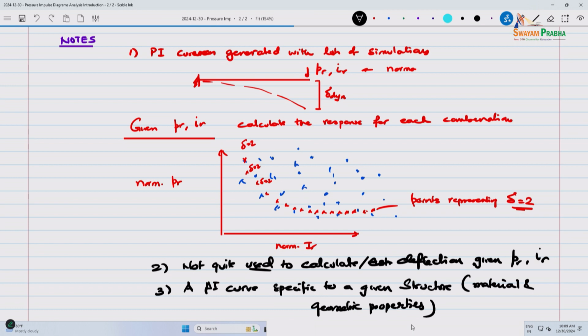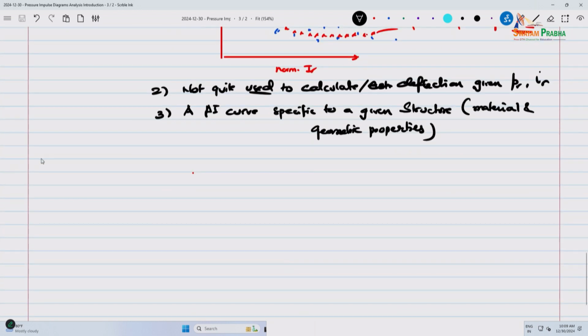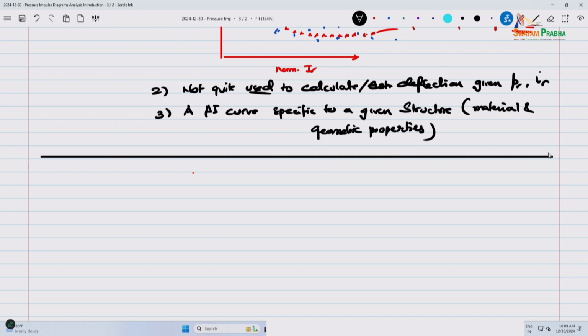So the next one I've talked about, but maybe we'll just give it a number anyway. For example, let's say you're given an elastic behavior and K is equal to 20 kips per inch and W by G, which is mass, is 12.5 pound second square per inch.